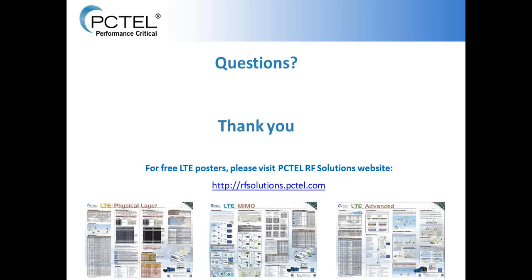And as I mentioned in the webinar, there's a lot of them that have been handed out by the operators, or have been used by people throughout the years, in the 90s and 2000s. And now a lot of the spectrum is being refarmed, and these BDAs and repeaters are not being turned off. So there are a lot of them out there, and they're really causing a lot of interference problems, both in building and outside with macro cells.